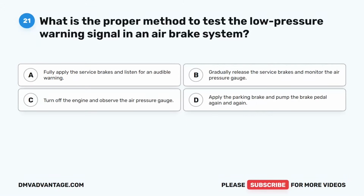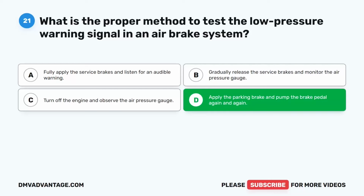Question 21. What is the proper method to test the low-pressure warning signal in an air brake system? A. Fully apply the service brakes and listen for an audible warning. B. Gradually release the service brakes and monitor the air pressure gauge. C. Turn off the engine and observe the air pressure gauge. D. Apply the parking brake and pump the brake pedal again and again. The correct answer is D. Apply the parking brake and pump the brake pedal again and again.